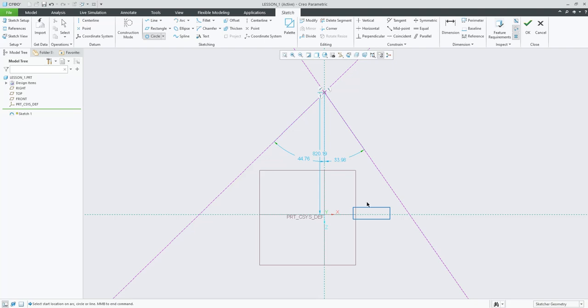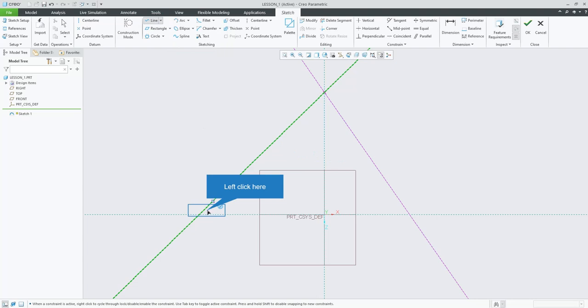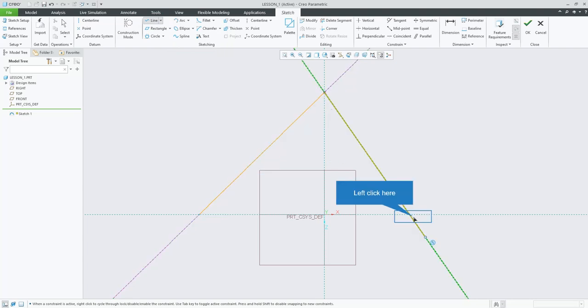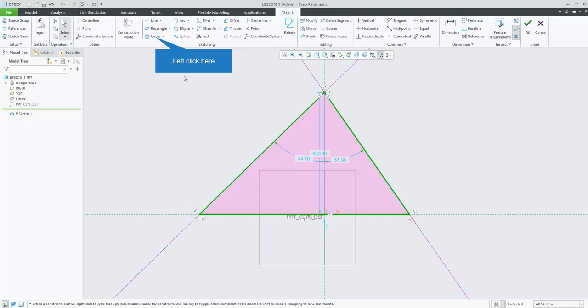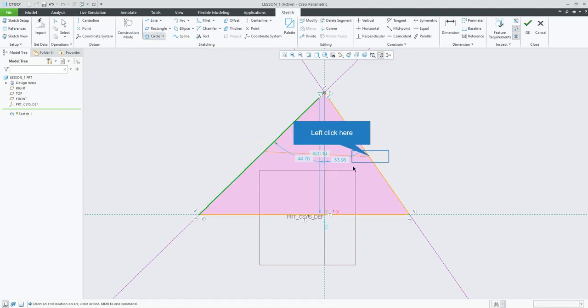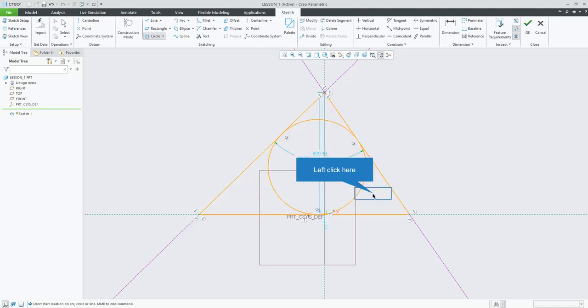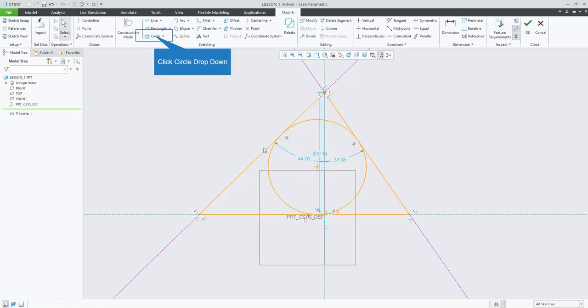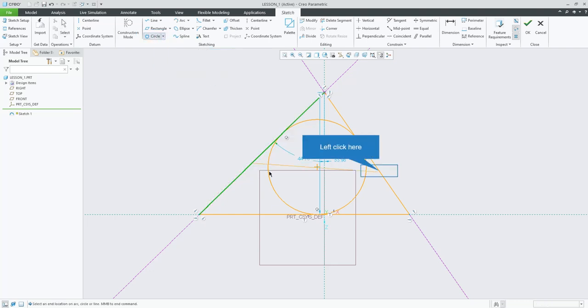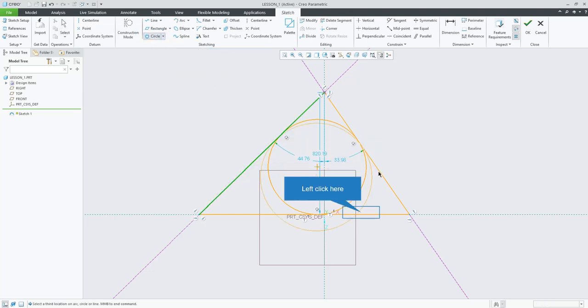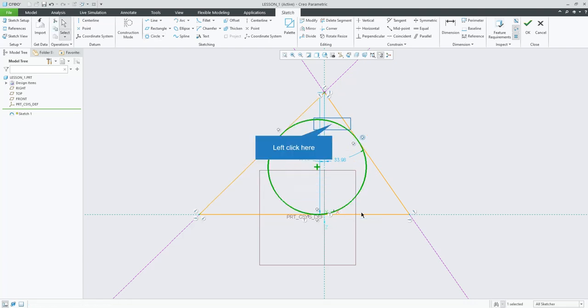How's it going to work for me? Will not work with references? Well, maybe it won't work with construction lines. It used to. No, it won't work with construction lines. So it has to be a line. But if you click on the one line, click on the second line, and then click on your third line, and it'll draw a circle with 3 tangent points, and those constraints will be there. You can see them right there. That's a tangent constraint.